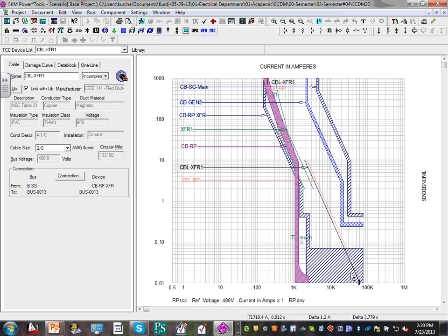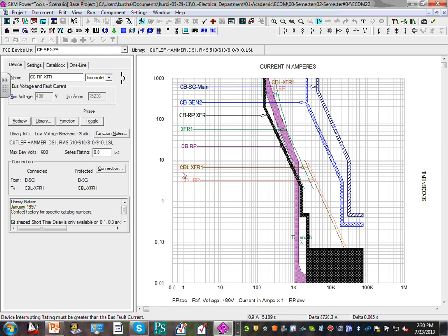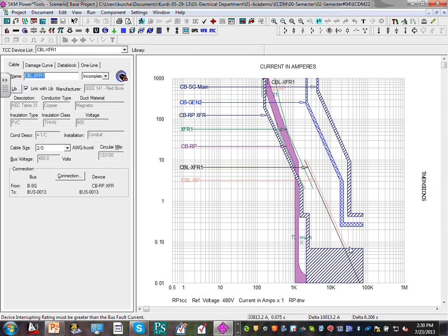If so, you can see right here the receptacle, this circuit breaker right at this point. If the short circuit is that high at the bottom, it might damage some of this circuit breaker right in here. But this circuit breaker, the secondary, I know the available short circuit stops right here, so it's not going to damage it. The primary though, my conductor at this point here will be a race between the circuit breaker tripping and the conductor starting to heat up, because it's a very high short circuit on the primary side at 480. So that's what I thought.